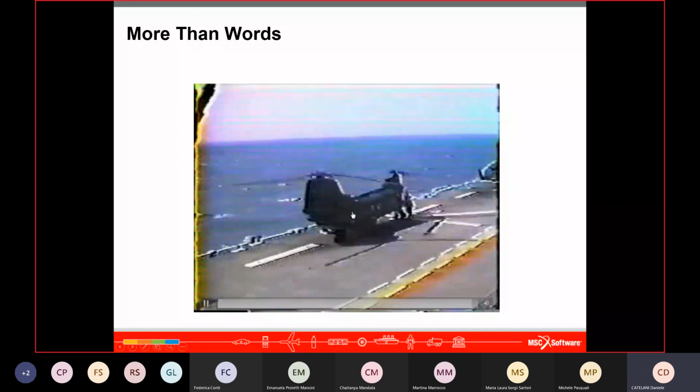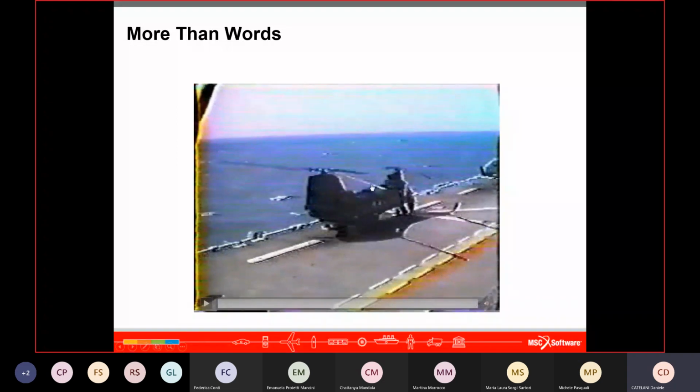So you have an excitation of a flapping movement, and in this case, this helicopter cannot fly anymore, because probably the blade has cracks, and no pilot will want to fly a damaged helicopter. So you have to remove this helicopter from the flight line, with a great problem for the customer.